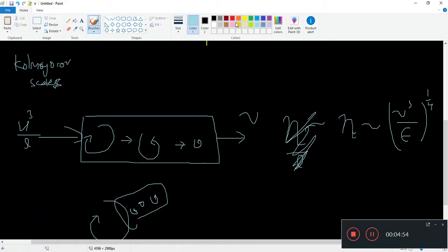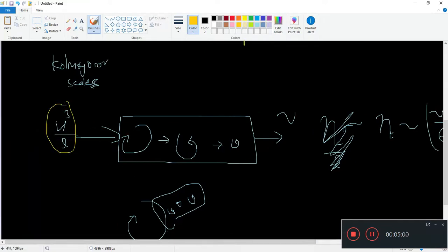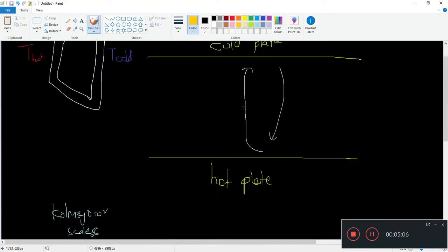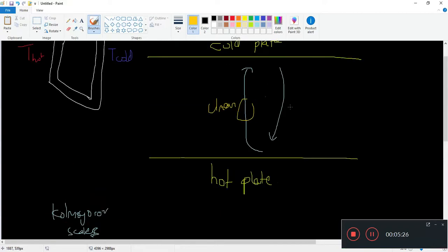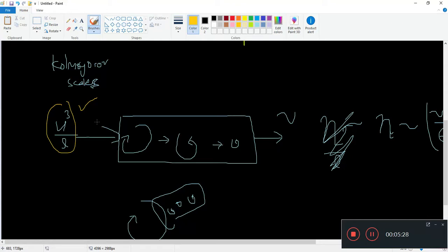Now, in natural convection, is this mechanism also true? You have some mean flow, which is fine. You have natural convection where buoyant, hot fluid rises, so you have a mean velocity, which is not due to some external driving force. It's not like you have a pump or a fan forcing the flow, but this is because of convection. So you have a different kind of driving force here to drive these eddies, but you still have some mean velocity that's creating these eddies if it's fast enough.